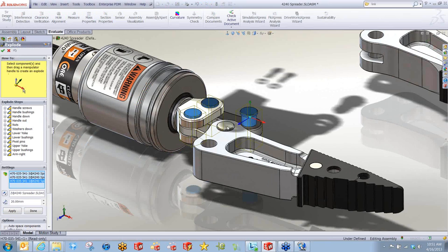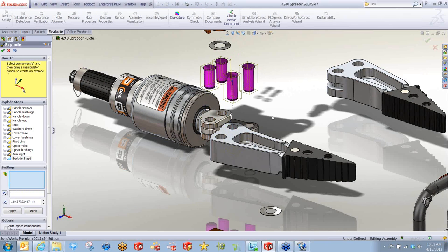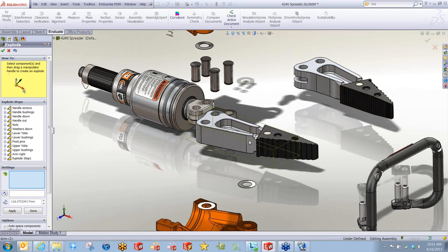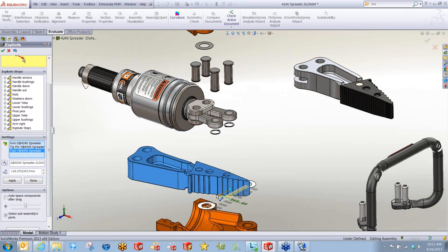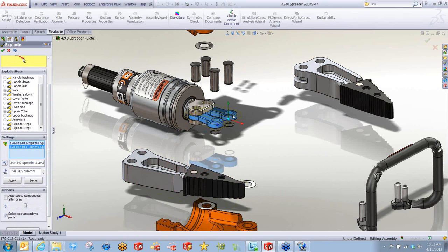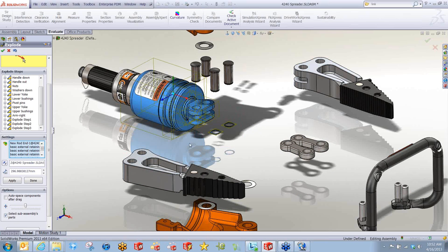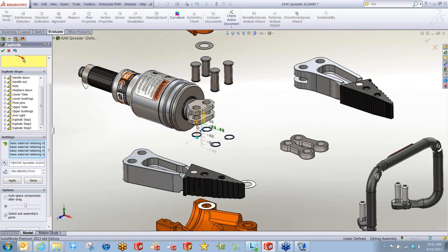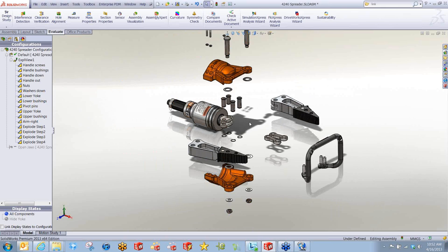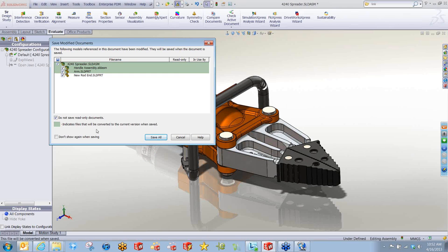Okay, all I've got to do to create these is just add parts, and then pick which direction I want to pull it. Y direction, arrow in the Y direction. Okay, we'll grab these parts, and we'll fan them out, pull them off to the side. Grab our links and pull those out. And then our retaining rings last. Pull those down. Okay, so it's that fast to create an exploded view of parts. Okay, now that we've got that, we can go ahead and update our assembly.